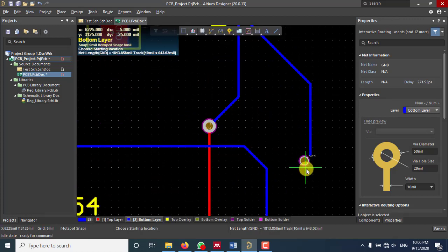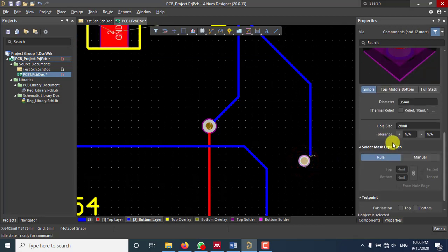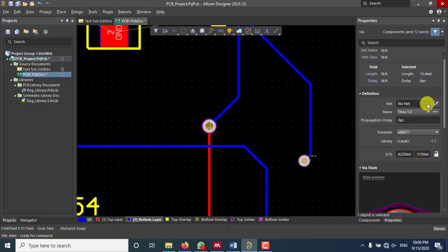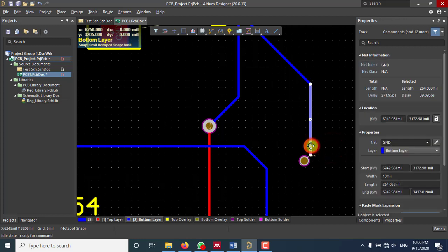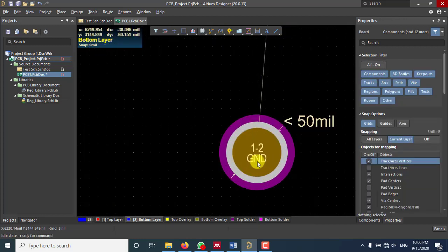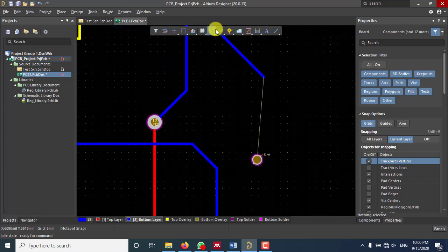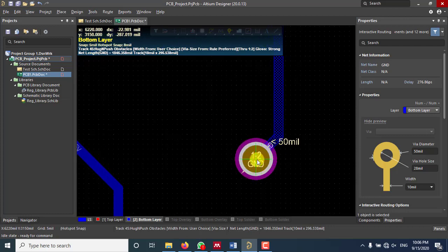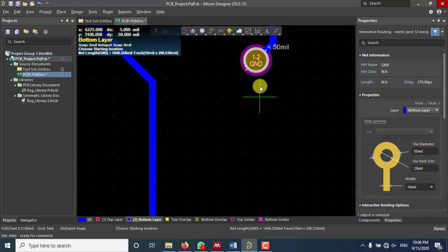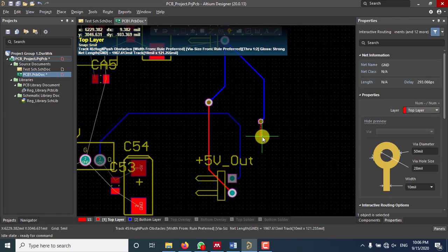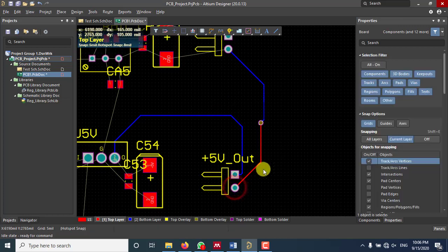So if you want to use it for connecting that ground, you should assign it the net GND. Now let me try again. Now you can see GND is displayed, and if I get there, you can see that I can connect, and from here on I need to press L to change the color, and then I can connect here.